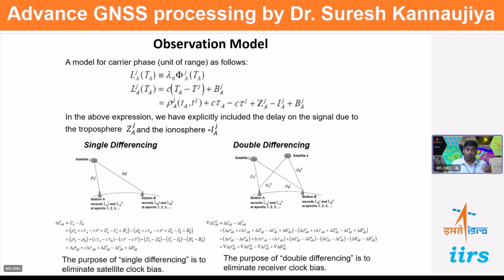If buildings are there, if trees are there, if canopies or obstructions are there, it creates multipath. So we need to remove the multipath from the observation. You have already seen the choke ring antenna. This concentric set of rings helps us eliminate the multipath. When the signal hits the concentric rings, it is reflected back to the obstructions, the building or canopy, and there it changes the polarization.